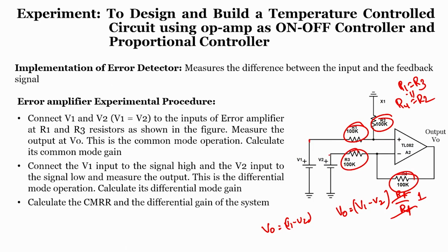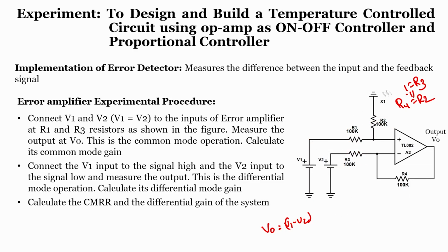So, that may be the problem with an instrumentation amplifier. Few instrumentation amplifiers have a gain starting from 5; for the commercially available monolithic instrumentation amplifier ICs, the minimum gain is 5. Since that is not possible in this case, we have to go with a high input impedance differential amplifier. So, we already know how it works. Let me quickly look into the simulation.